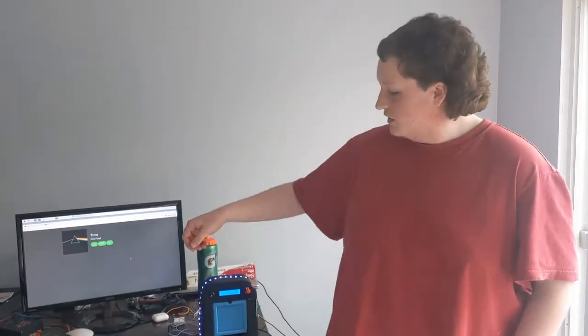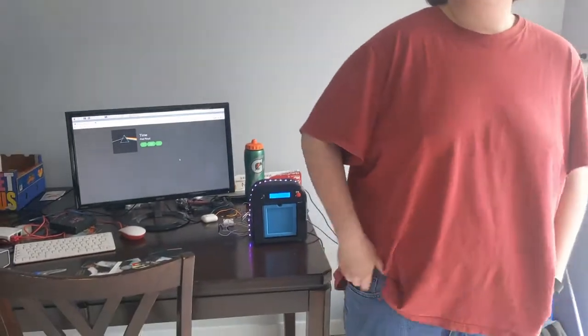I'm going to be talking about the communication protocols that the Pi Jukebox system uses. The first communication I'm going to talk about is the jukebox to the Arduino that controls the LCD screen on the front here. That's done over UART USB serial communication, and with that we're able to send strings to the Arduino so that we can display both the song name and the artist name that created it of the song that's playing right now.